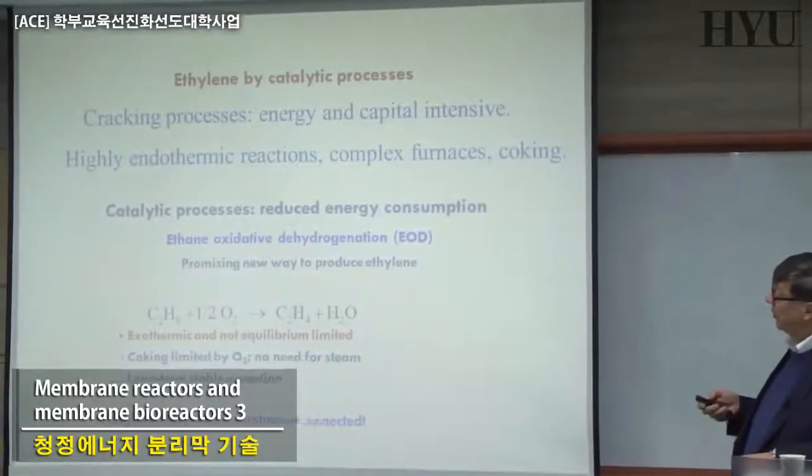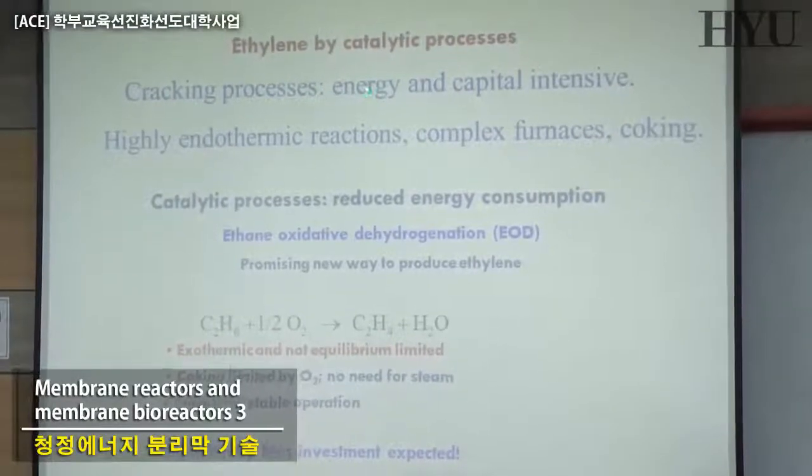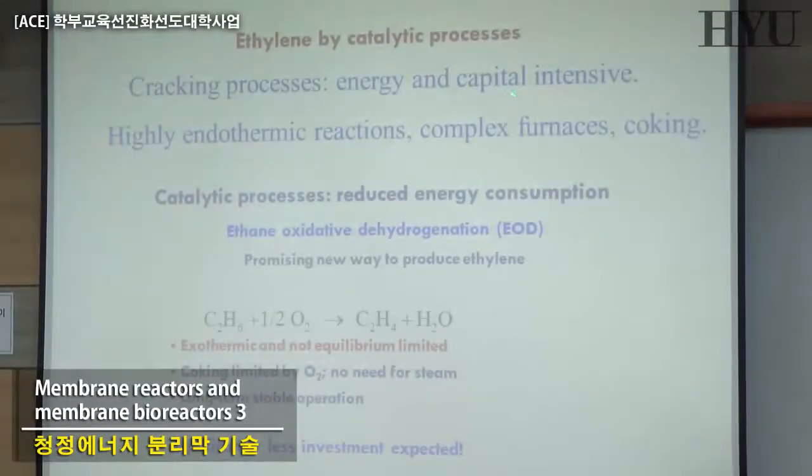And perovskite is quite interesting because today the cracking process is energy and capital intensive, so it's quite expensive. It is a highly endothermic reaction, and you need a high temperature, a big, complicated furnace, coking, etc. You can try to reduce this.